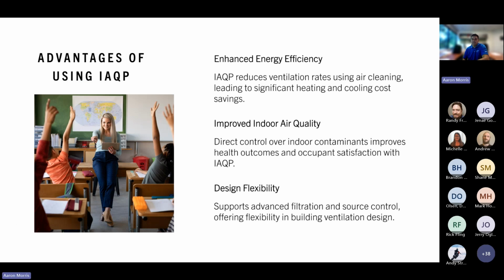What are some of the advantages of using the IAQP method? Enhanced energy efficiency. When we go through this process, you can reduce the amount of outside air required and therefore reduce the energy required to treat that outside air. You can improve the indoor air quality even with less ventilation because you're using a strategy to specifically target the contaminants of concern. And it could provide design flexibility.